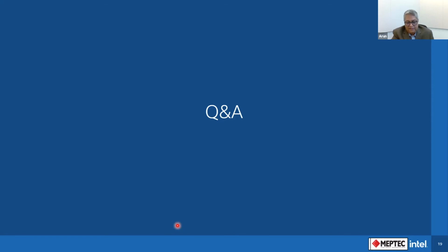Because even though we have a post packaging class test, the best thing is to get a known good die at the wafer. So everybody wants to do all testing, especially in the multi-chip era, right? Even one chip faulty means you throw away every die on the package. So we want to test everything at wafer probe. So temperature control at wafer probe is becoming a problem.